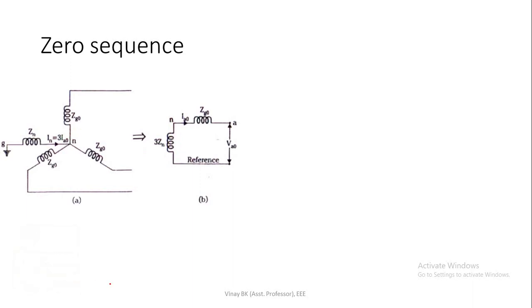So how are we getting this zero sequence voltage? It is the current of 3 IA0. The current of 3 IA0 produces a drop in the impedance. So here the drop is nothing but 3 IA0 into Zn, in the neutral impedance Zn. To show in a single phase equivalent zero sequence network the same drop when current IA0 flows, the impedance should be 3 into Zn. To get the same value of drop, the impedance should be 3 into Zn.